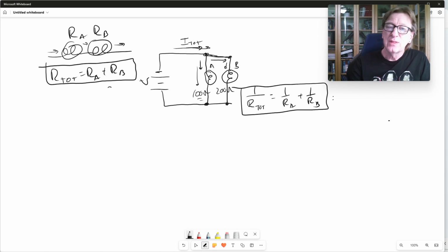And so that's one reason why trying to wire too many things into your circuit can actually cause a problem. I generally want them in parallel. That way, if for some reason this one dies, the other one doesn't die as well, which would happen if they were in series. But the more loads I add to the circuit, the lower the total resistance is going to be, which means for the same voltage, I'm increasing the current. And if I increase that current draw, well, if my robot can't provide it, then it's going to brown out or it's going to fry from that.